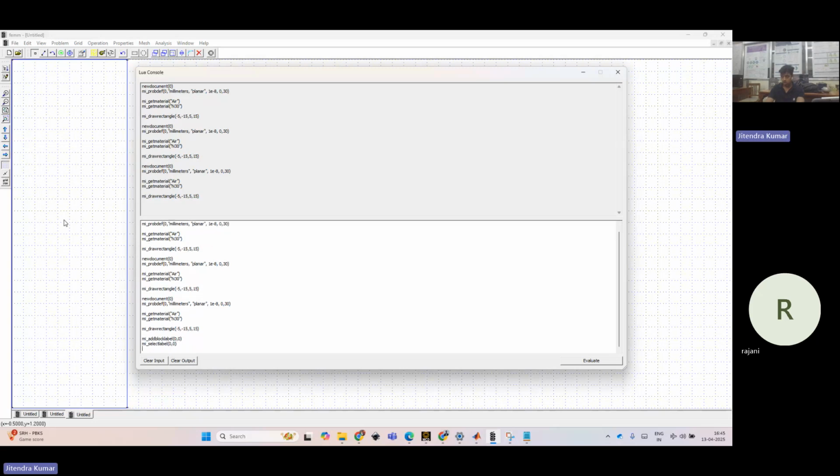Okay. Now we are going to define this label with the material which we created, right? So mi_setblockprop with N30, the material which we created.